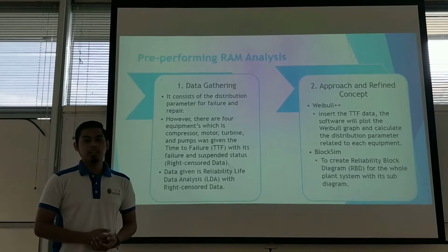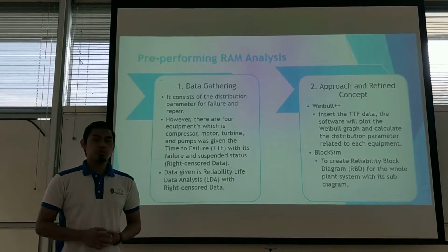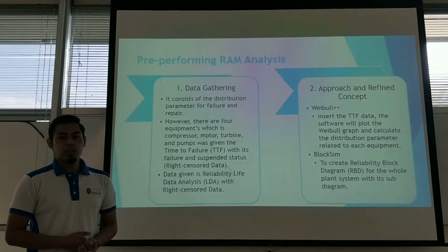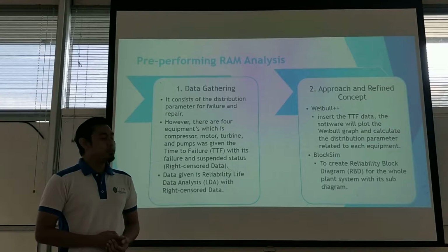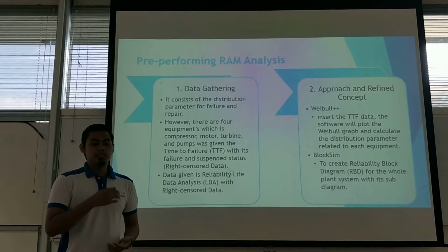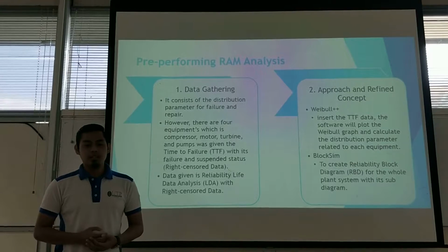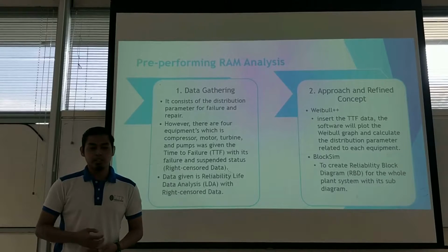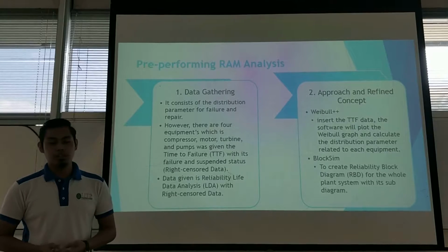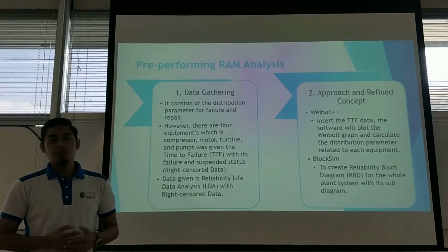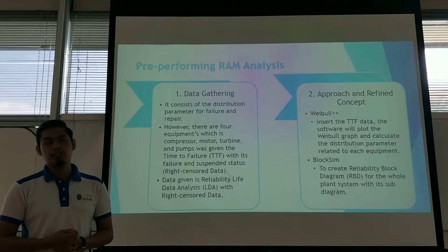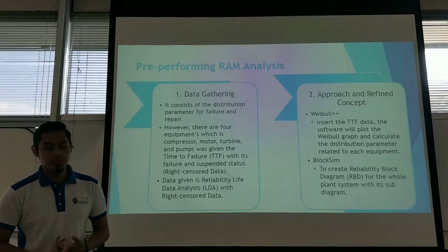So for this analysis, we choose 2 software, which is Weibull++ and BlockSim, to run our analysis. The first one is Weibull++ software. The Weibull software is used to insert the TTF data, and then the software will plot the Weibull graph and calculate the distribution parameters related to each of the 4 equipment. From this stage, we have complete data for the failure distribution parameter and repair distribution parameter.